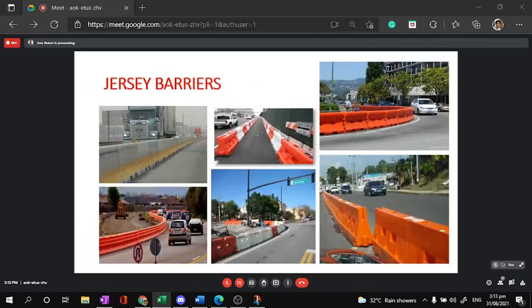The other one is bigger in size. This is more for really big arterial highways. We call this a Jersey barrier. You can see these placed by the RTA when they have to improve the road channelization during peak time in Carmen, Rotonda, and so forth on the highway. So these are blocks of plastic which guide traffic with yellow and orange painting. This will guide them along the road network so that they will really follow the channeling of traffic when there is road construction, when there's a division between trucks and regular motorists on one side, or if there are road sections that have to be channeled because of improvements or widening of the road, etc. So these are Jersey barriers.